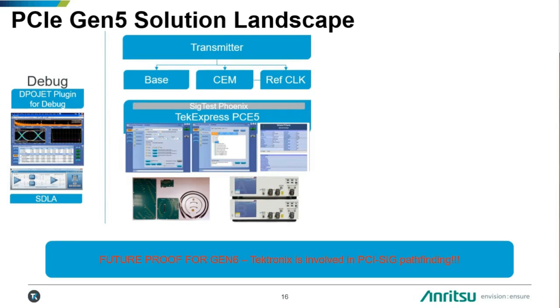For transmitter testing, Tektronix has fully automated solutions using our TekExpress software. For base, CEM, and ref clock, ref clock has the ability to call the Silicon Labs tool, which is a very capable analysis tool for ref clock testing, and that's fully integrated into the solution. You can also see test fixtures below. These are pre-compliance fixtures that are available to support our customers until Gen 5 CEM fixtures are available from the PCI-SIG.